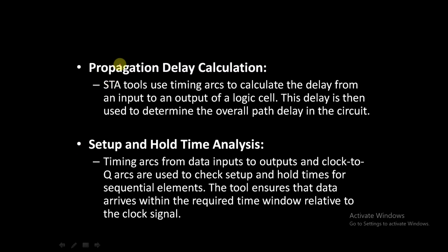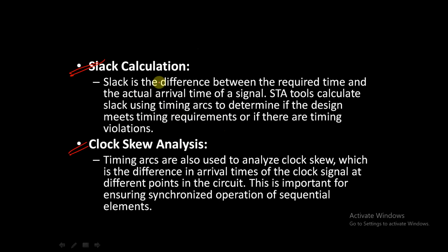Clock skew analysis will be done by the tool using these timing arcs. Before discussing these calculations, we will move forward, and after completing the definitions of setup time, hold time, slew, and slack, we'll come back to this and see how the tool is performing.